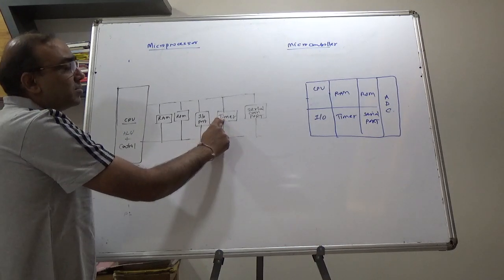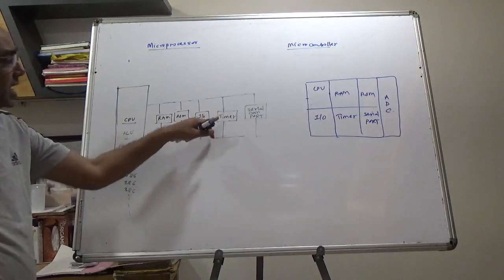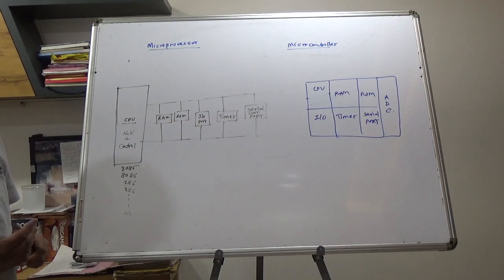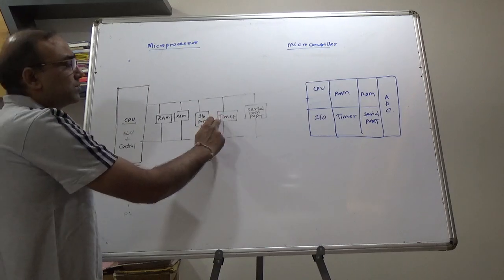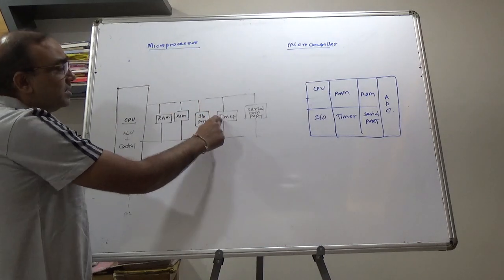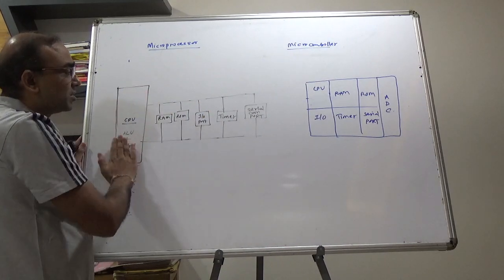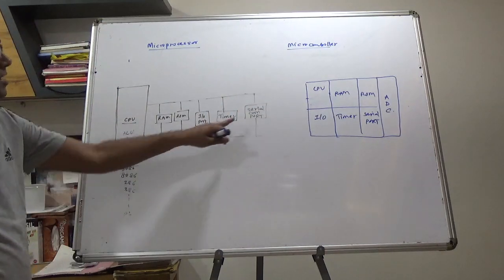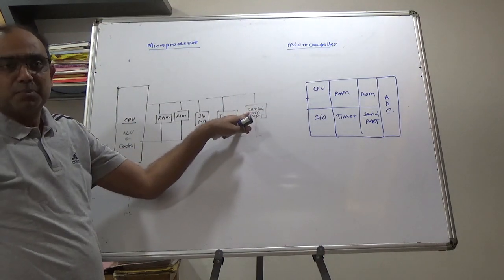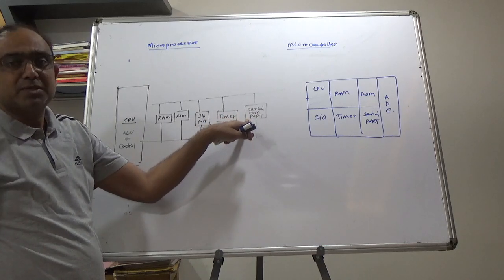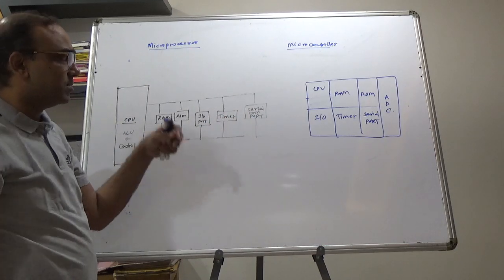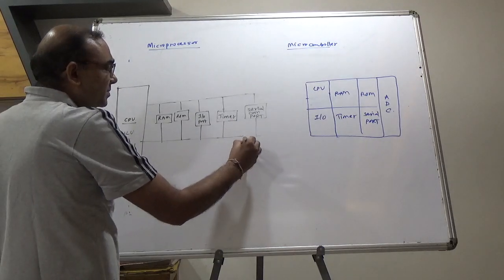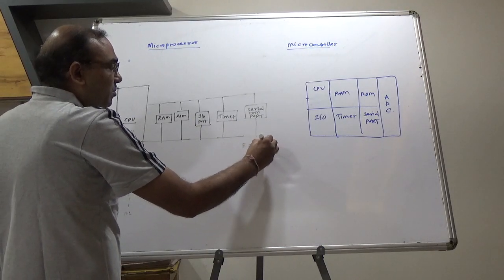There is also something called timer chips. Timer chips are needed for time-centric operations, where we have to consider delays and all that. So these are timer chips interfaced with your CPU on a motherboard, and there will be a serial port. Actually, USB port is what we use nowadays as an example of a serial port, but in older computers you can find RS-232 type of ports.